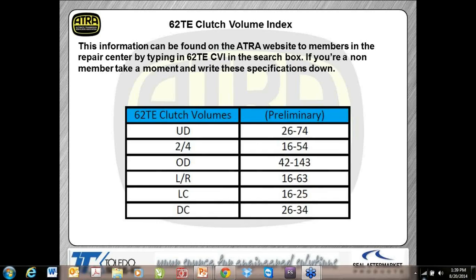Now, I like to air check with 30 psi. Sometimes you can overcome a leak that you won't even hear when you're using regular full shop air. So I actually put a paint regulator on the back of my blow gun so I can regulate the air pressure down.